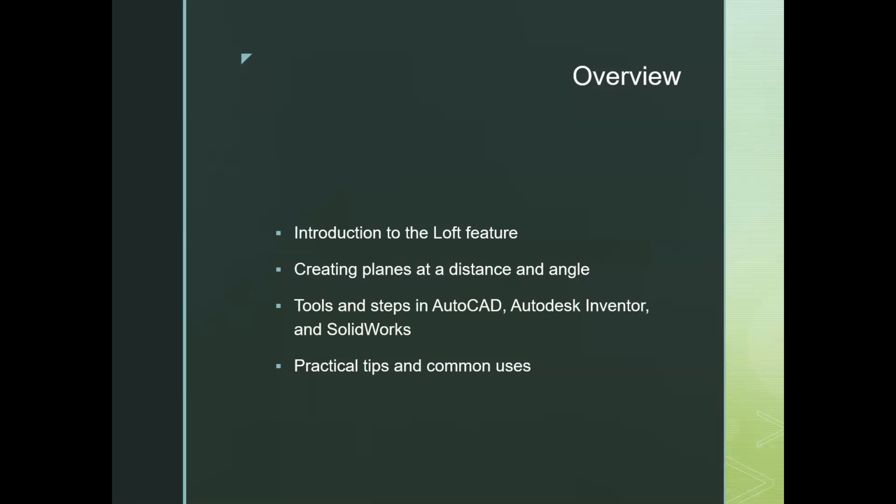So these are probably the four most commonly used features that you can create any 3D design with. It's only four of them, and these are the tools you're going to use. Now the Loft feature, what sets it apart from everything else is that it has to be on different elevations, okay? So different elevations, different planes, and things of that nature.